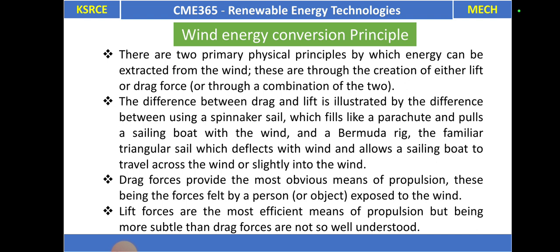The lift is produced by the change in velocity of airstream which speeds up the air flow, thereby creating a pressure drop. The pressure drop forces the lift surface from high pressure side to low pressure side of an aerofoil. If the air pressure increases on the low pressure side, enormous turbulence is produced which reduces the lift force and it leads to increase in the drag significantly, called stalling.